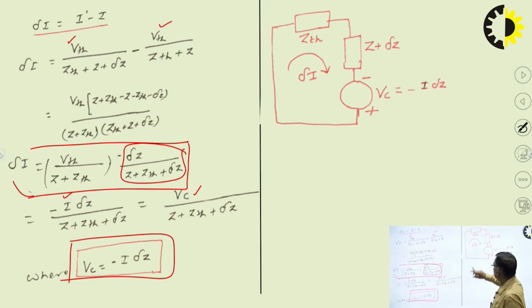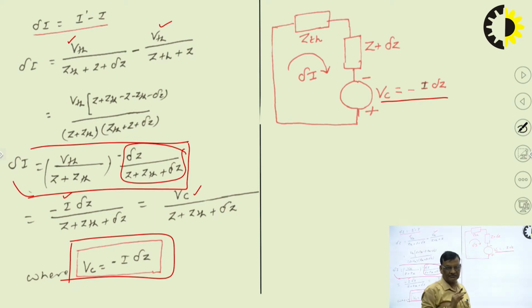Now this is another circuit, the circuit for the compensation theorem. Here we have injected this voltage into the modified branch, where the change has taken place. Then we replace the independent source VTH by its internal impedance. An ideal voltage source has zero resistance, so it is replaced by a zero-resistance wire, which looks like a short circuit.